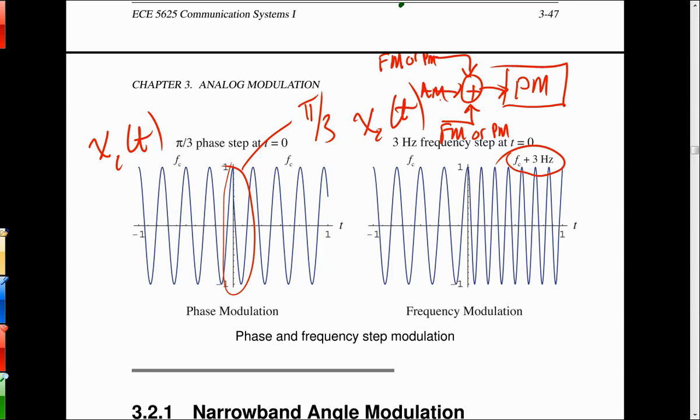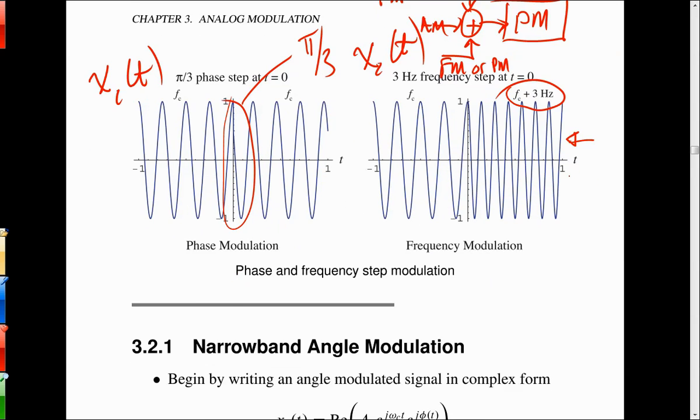Remember when I was talking about listening to a fax machine? That would be this waveform over here. Frequency shift keying, you could have the carrier shift high and low with ones and zeros, and that's one of the original digital types of modulation. It used FSK as frequency shift keying. Gaussian FSK is what Bluetooth uses. It's not that far away from frequency shift keying. It's just got a pulse shape modification, and so on from there.